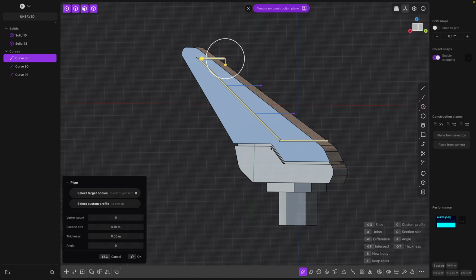So same as the width of the line that we created down here using that other technique. I want this panel line actually to be a little bit smaller. So if I go like 0.75 here, that'll make us a 0.15 millimeter panel line, as if we had used a 0.15 millimeter chisel, right? Except that it's a rounded panel line, so rather than being squared off edges like this one here, it'll have rounded edges. So it won't be exactly like we used a chisel, because a chisel would give us those nice square edges, right?